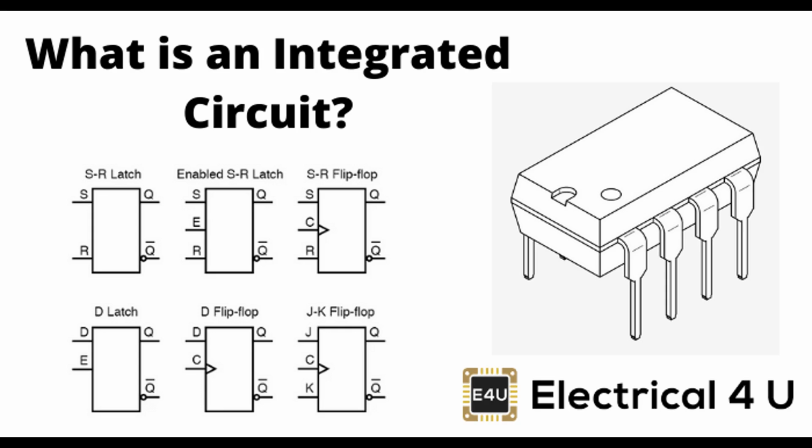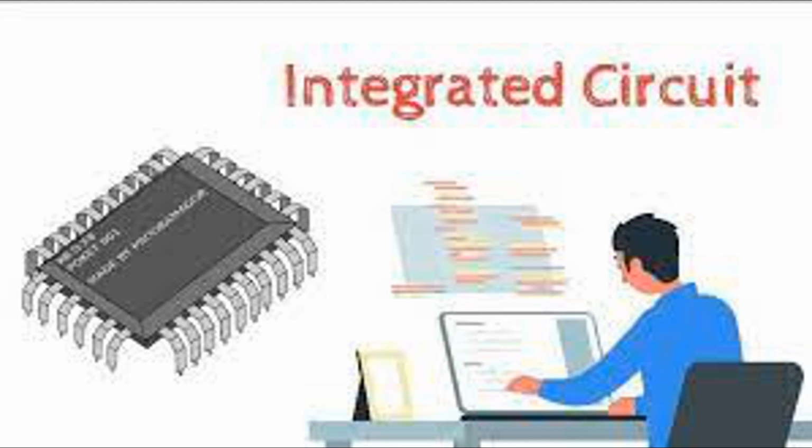These basic logic gates can be combined to create more complex logic circuits that perform various logical and arithmetic operations. Digital systems are built by connecting these gates in specific configurations to perform specific tasks, such as data processing, memory storage, control, and decision-making. Combinational logic is a fundamental concept in digital electronics that refers to a type of digital circuit or system in which the output is solely determined by the current combination of inputs and is not influenced by previous inputs or the circuit state.